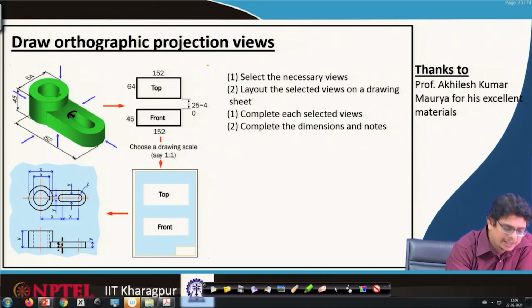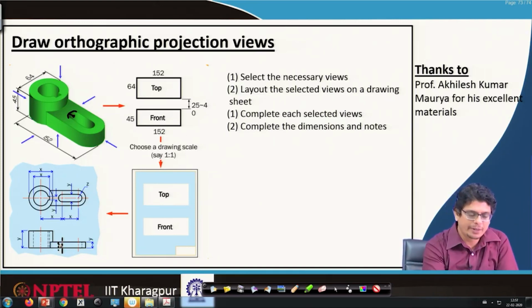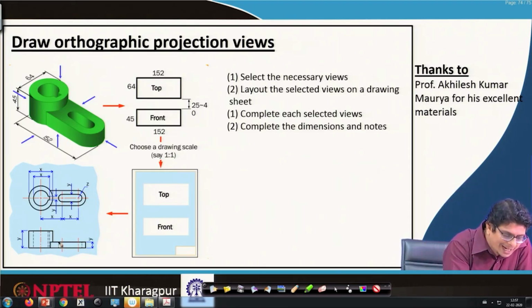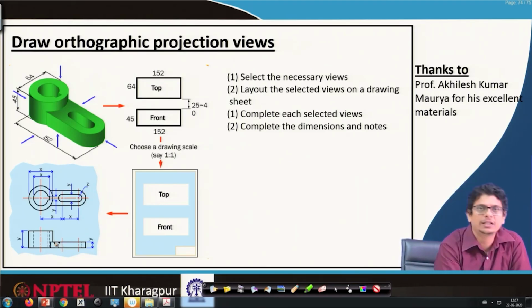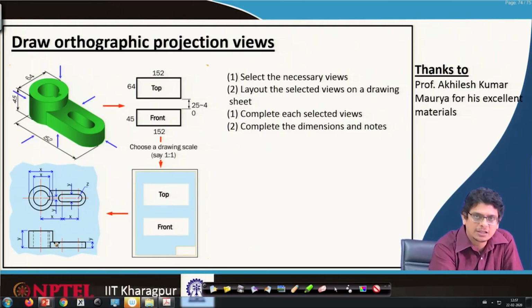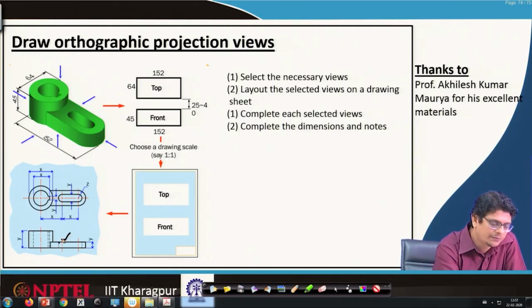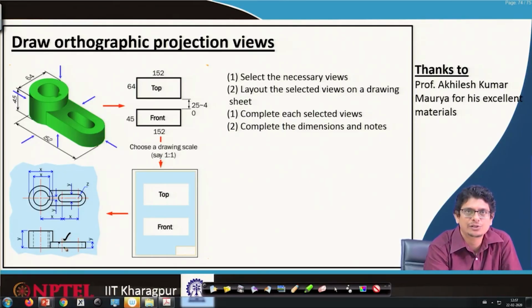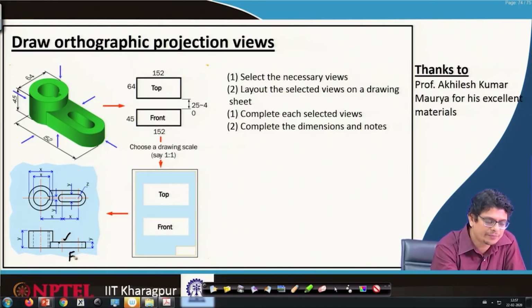So, we show it by a dashed line. Wherever material is removed, that portion we show by dashes, localized within that object. Whenever there is a center and a radius scooped out from that direction, we show it by an axis which comes out of that object also, more like an extension kind of line. This is for the front view.